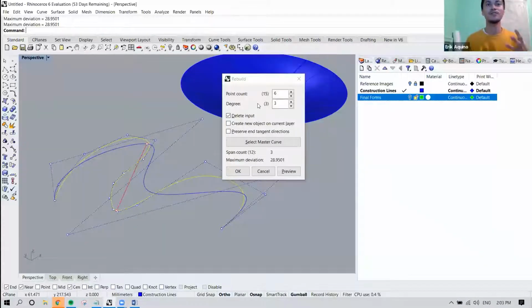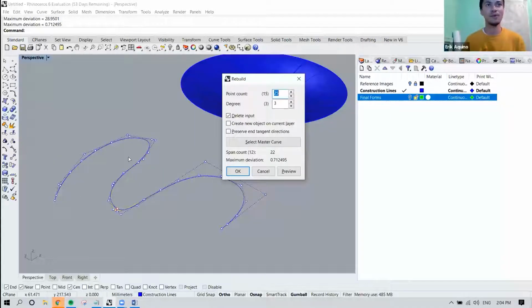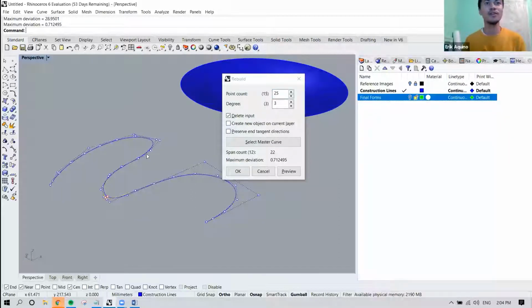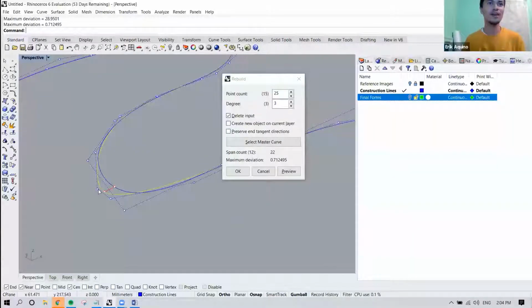So this is a way to modify your curve if you want it to have more adjustments, like if we're having more points, and it'll also separate your control points in even spacing. So that makes it a lot nicer to create smoother curves and modify it generally as opposed to locally. And what I mean by locally is that when you have a lot of control points bunched together, then you're not really spreading that modification along the curve. You're just locally changing it with that cluster of points.